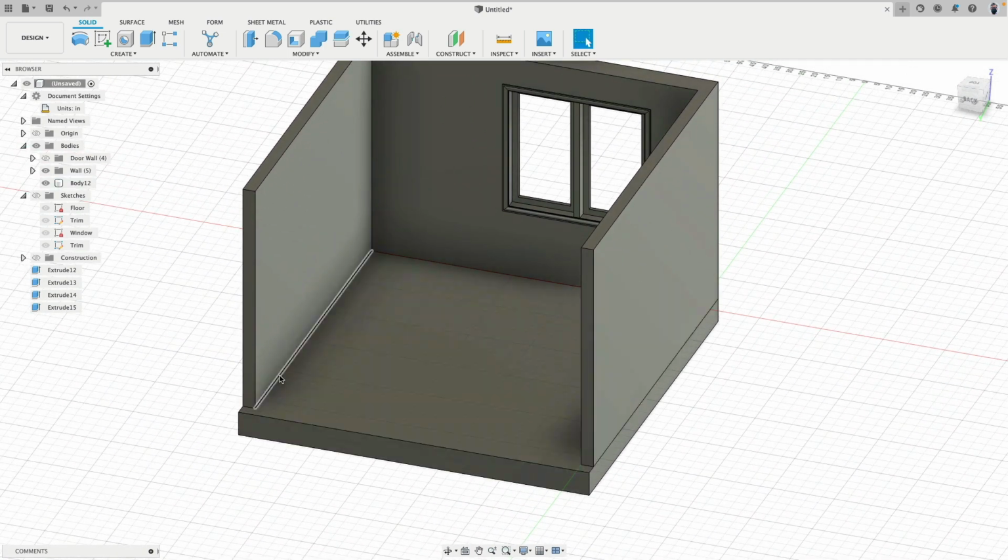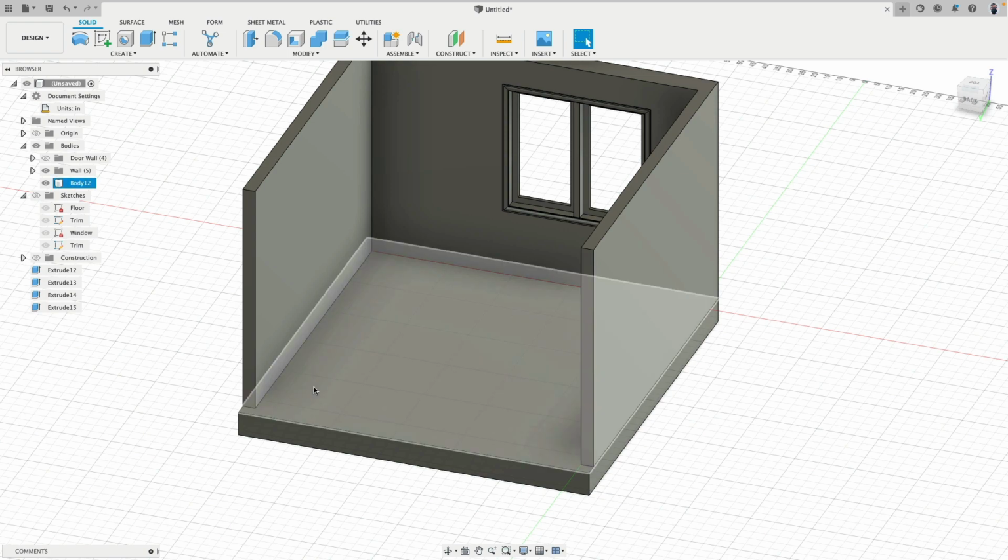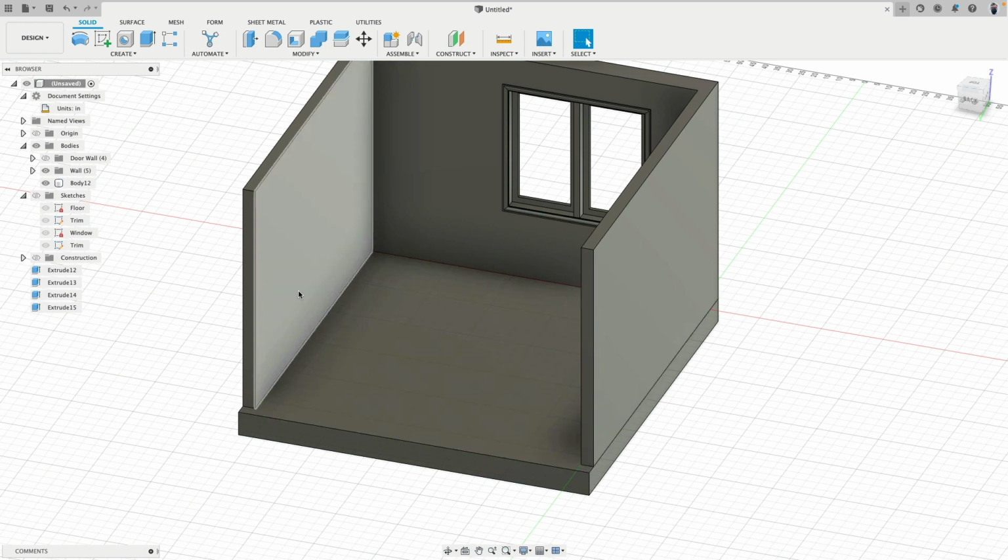On the bottom here, we will have a little bit of a baseboard. The floor, let's say, is actually hardwood floor. Hardwood floor is not connected to the walls because during winter and summer, humidity changes, the material expands and shrinks, so it needs to have space to breathe. So we will create a small baseboard, and then we will create a small cover up too for the gap. So the baseboard actually comes first.